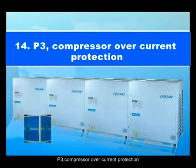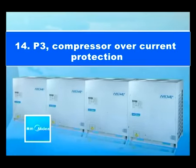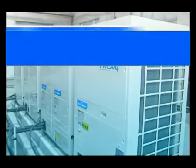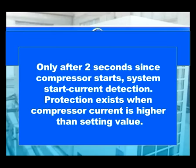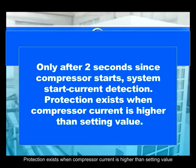E3. Compressor overcurrent protection. Only after 2 seconds since the compressor starts, the system starts current detection. Protection exists when the compressor current is higher than the setting value.